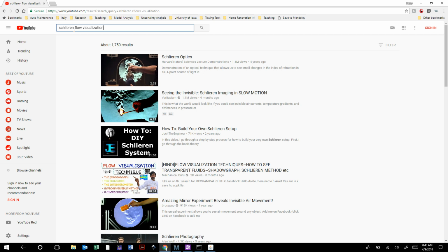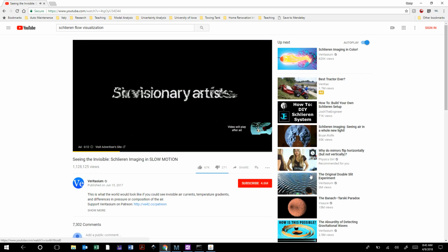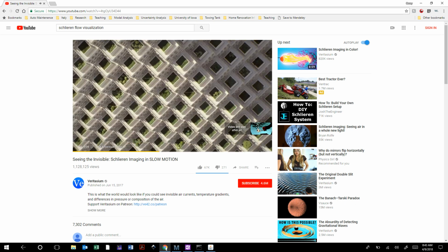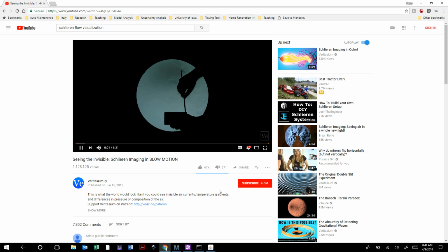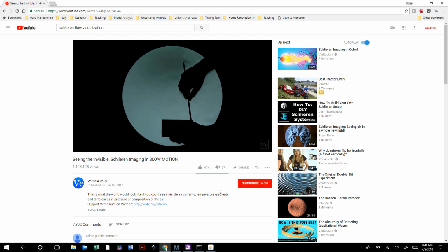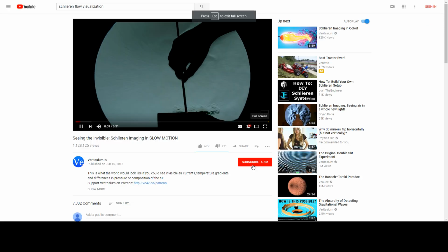All right. You can see this very clearly in this technique known as schlieren visualization. So I'm not sure this is the same video that I saw before, but any of them should get the point across. Okay, we get to watch this whole advertisement. So schlieren visualization is a way, using some mirrors and cameras, to basically amplify the change in refractive index of gas, which is temperature dependent. So it's a way of essentially visualizing the flow of thermal energy in air.